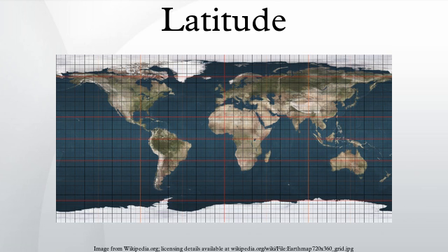the ISO 19111 standard. Since there are many different reference ellipsoids, the latitude of a feature on the surface is not unique. This is stressed in the ISO standard, which states that without the full specification of the coordinate reference system, coordinates are ambiguous at best and meaningless at worst. This is of great importance in accurate applications, such as GPS, but in common usage, where high accuracy is not required, the reference ellipsoid is not usually stated.